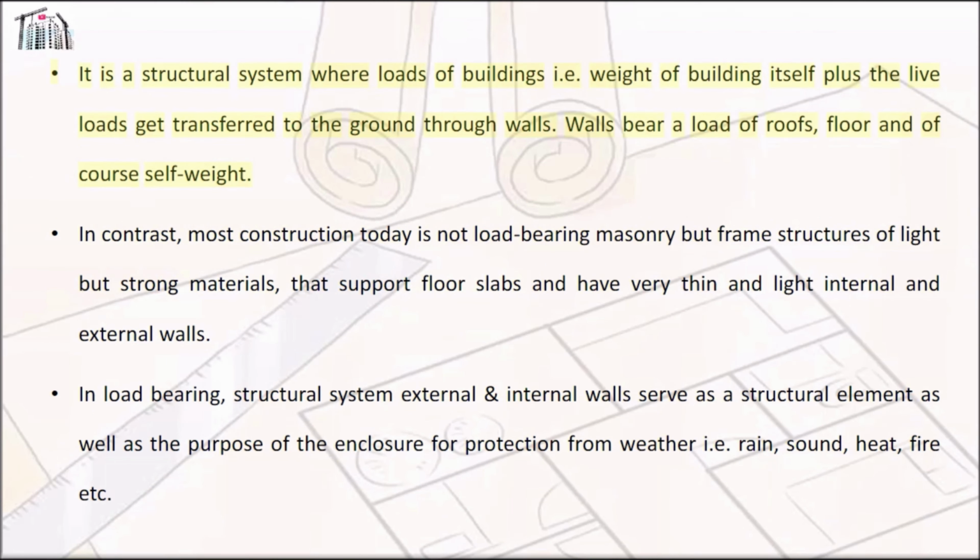It is a structural system where loads of buildings, i.e. the weight of the building itself plus the live loads, get transferred to the ground through walls. Walls bear the load of roofs, floors and of course self-weight. In contrast, most construction today is not load-bearing masonry but frame structures of light but strong materials that support floor slabs and have very thin and light internal and external walls.